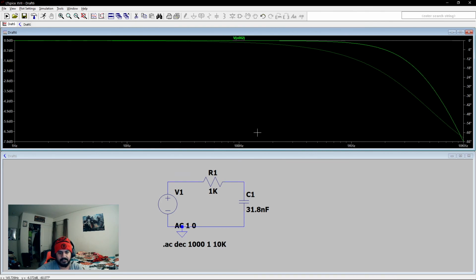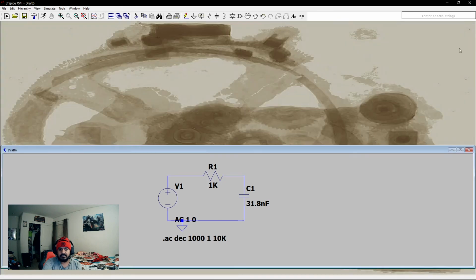But as you can see, you would use AC analysis especially when you're working with filters or any circuit that has to do with the frequency domain, where different frequencies would affect the circuit in different ways. So now that we know about these different SPICE directives, we can get into an example using one of them, which is going to be AC analysis, and we'll do a low pass filter design, basically the same exact design that we did in the MATLAB workshop, but in LTspice, so you can see the difference between MATLAB and LTspice for the same circuit.